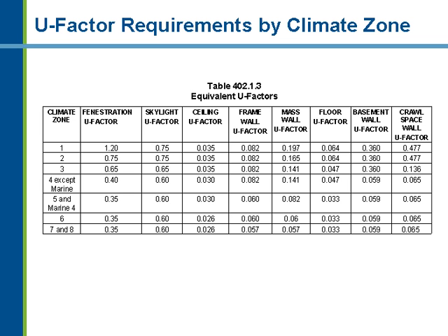So on the U factor table, you're not going to see the solar heat gain. You still have to go over to the R value table for the solar heat gain requirements. But again, they're all based on climate zone. And they start out with fenestration and go over to skylights, ceilings, and so forth. And we're going to look at these in detail in the order that are given here and give some more information as far as fenestration, skylight, ceilings, and walls and so forth.